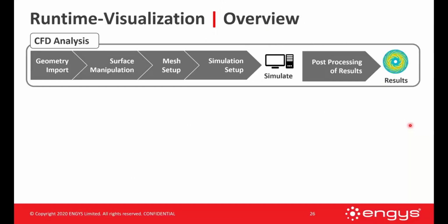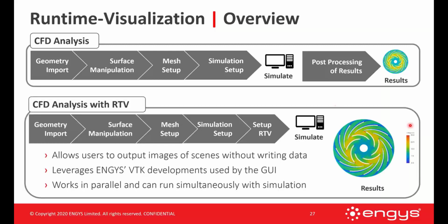Now, back to our CFD analysis overview. For a process that uses runtime visualization, instead of dedicating a lot of our time at the very end to loading these very heavy, cumbersome data sets to obtain results, we go through this process, and before we simulate, we set up our runtime visualization. That way, while we're simulating, we'll be able to instantly go to our meaningful end result.